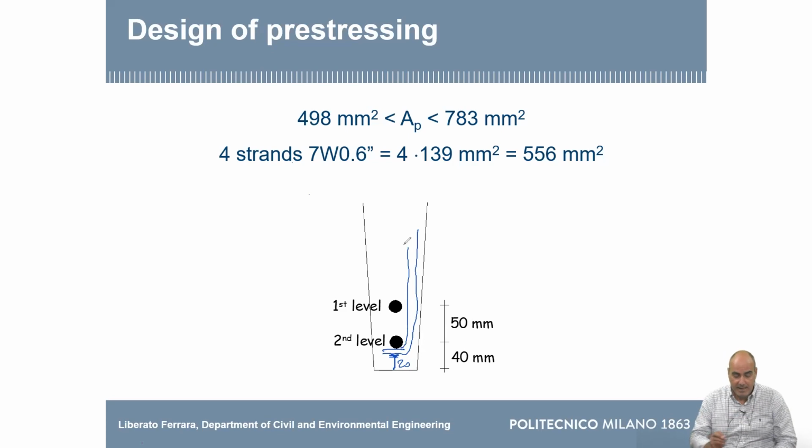This adds up. And then your first tendon, you have to consider that you always measure them from the center. So if it's 1.6 inches, there are another 8 millimeters more or less from there. So if you sum up 20 plus 8 plus 8, you get 36. Okay, let's say 40, you allow for some tolerances and so on. Then you also have some minimum spacing required between 2 tendons or 2 bars.